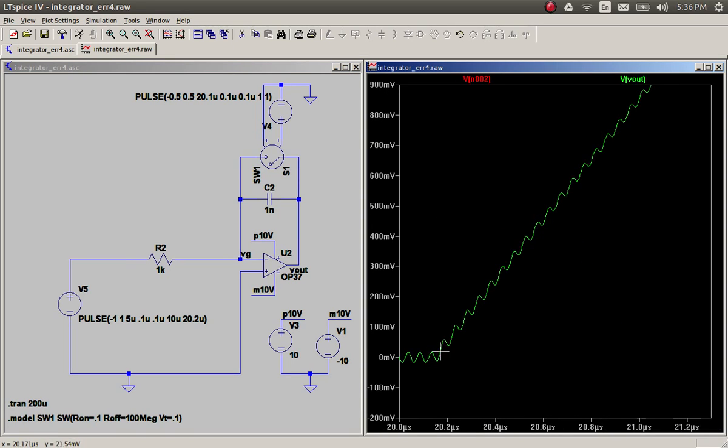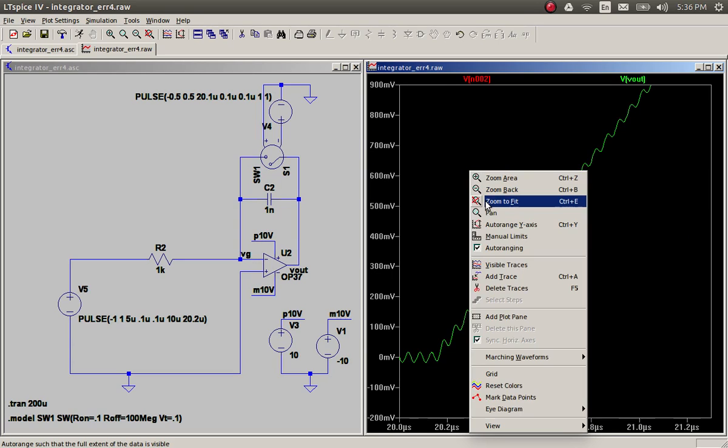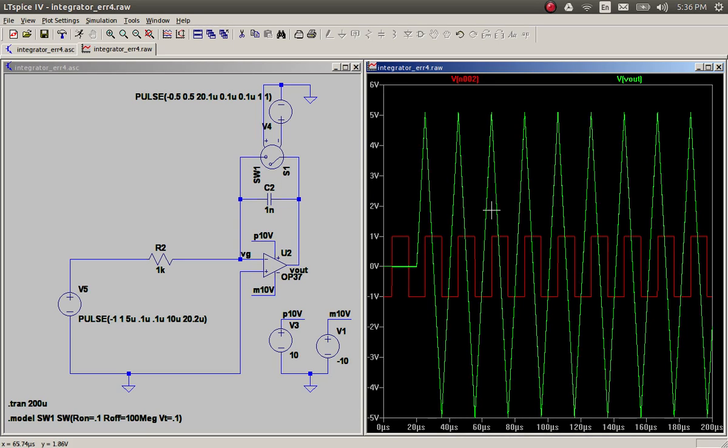There seems to be a lot of ripple and ringing, and we'll deal with these as we start understanding simulators and how they solve, and how to get better results than that. But for now, it may or may not be because of the amplifier, and it may also be with the way LTSpice is simulating. But it's interesting to know that when you put realistic components, you're going to get results a little different from what you expect from ideal results. So first, it's good to understand the ideal results, and then we get into, is this really noise or is it really ringing, and so on and so forth.